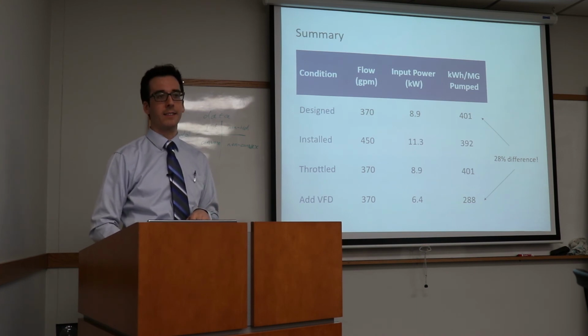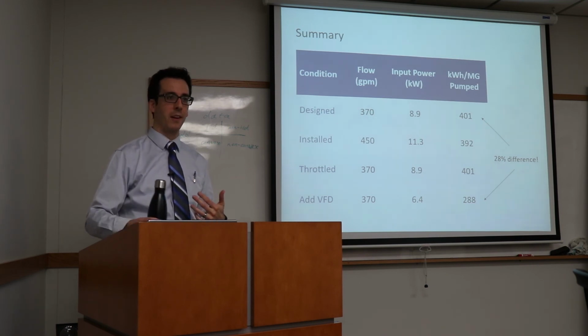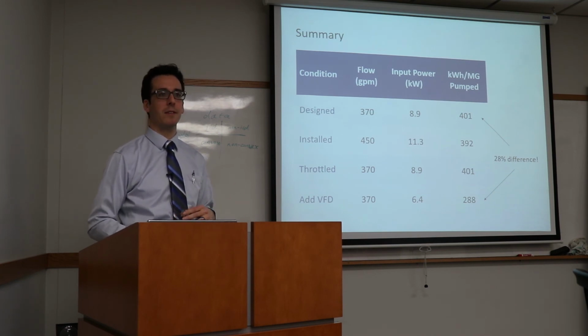And maybe that costs less than a VFD. A VFD gives you a little more operational control to respond to varying flow conditions. So it's just a good practice anyway. But if that's too cost prohibitive, trimming the impellers may work just as well.